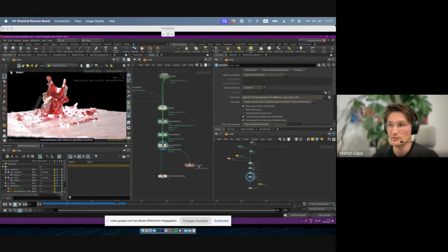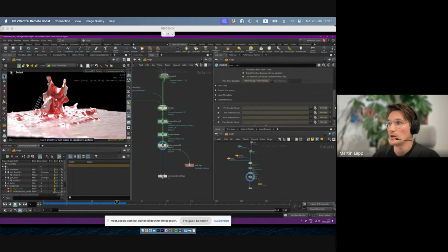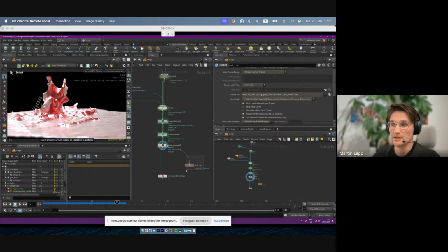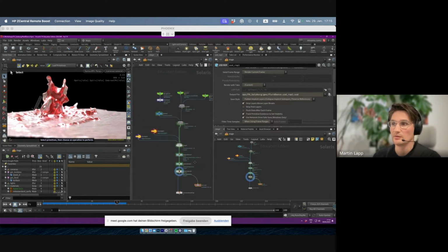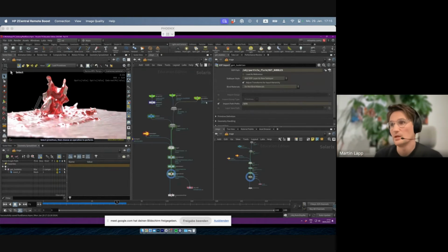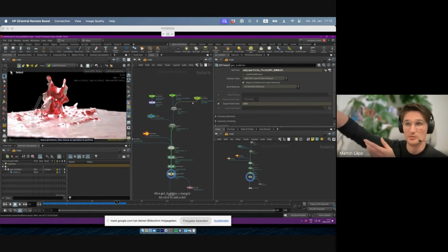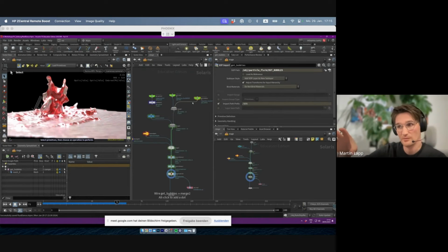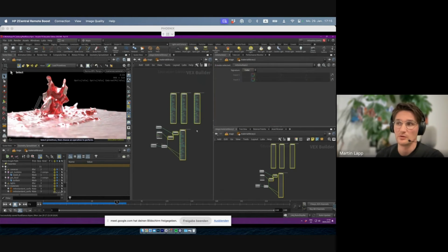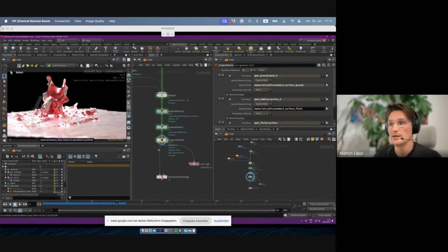And if I would write out this USD, depending on how I save it, it would be extremely lightweight, because it doesn't necessarily store the heavy geometry each frame. You can think of it almost like a text file where it says, my heavy geometry lives here, and then this camera data is added to this, and then these types of lights at these positions with these values on it are also referenced in. And then I'm creating these materials, which are also just text, basically. And then I'm assigning this to the geometry.